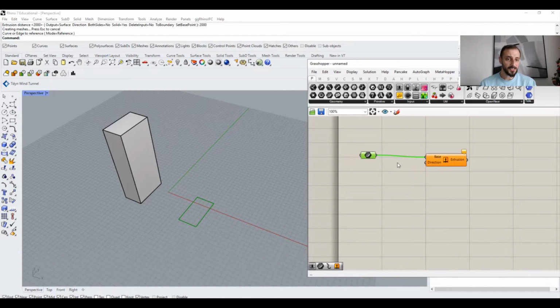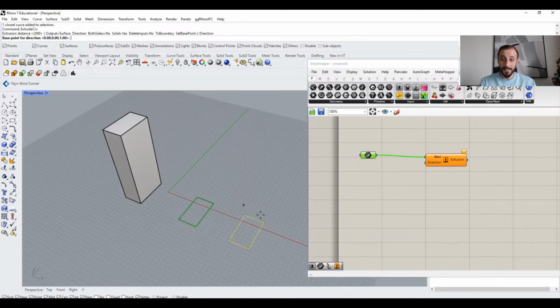And what is the direction? If I hover over here, it's asking me about the extrusion direction. If I switch back to this exercise, copy this here somewhere else just to show you something, and put extrude curve, you see it asks me about direction. In that case I haven't specified the direction, and if you haven't specified it, it goes only Z. But in Grasshopper, you have to put that in if you want to extrude this curve even into the Z direction.